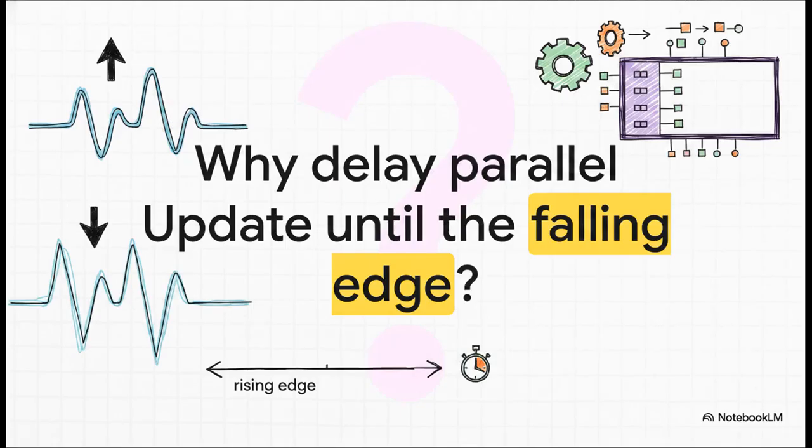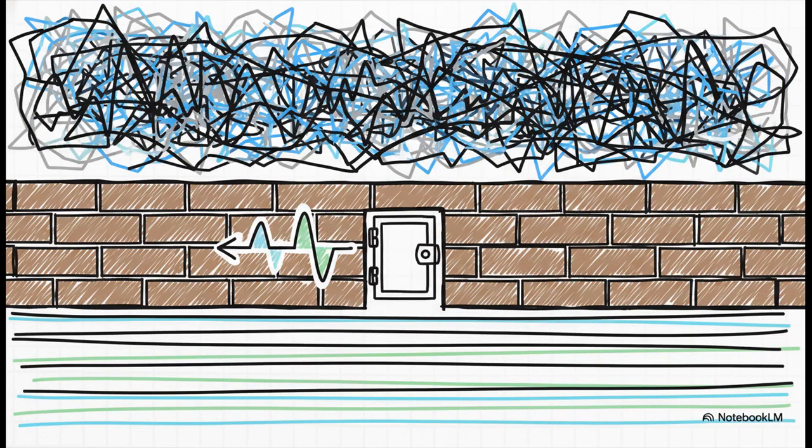Okay, I want to end on a question that really separates the novices from the true hardware experts. Throughout this entire explainer, I've been saying that the TCK engine drives state changes and shifts data on the rising edge of the clock. But the standard explicitly mandates that the actual latching of data, the parallel update in update IR and update DR, happens on the falling edge of TCK. Why the half-cycle delay? Think about it for a second. Here is your aha moment.